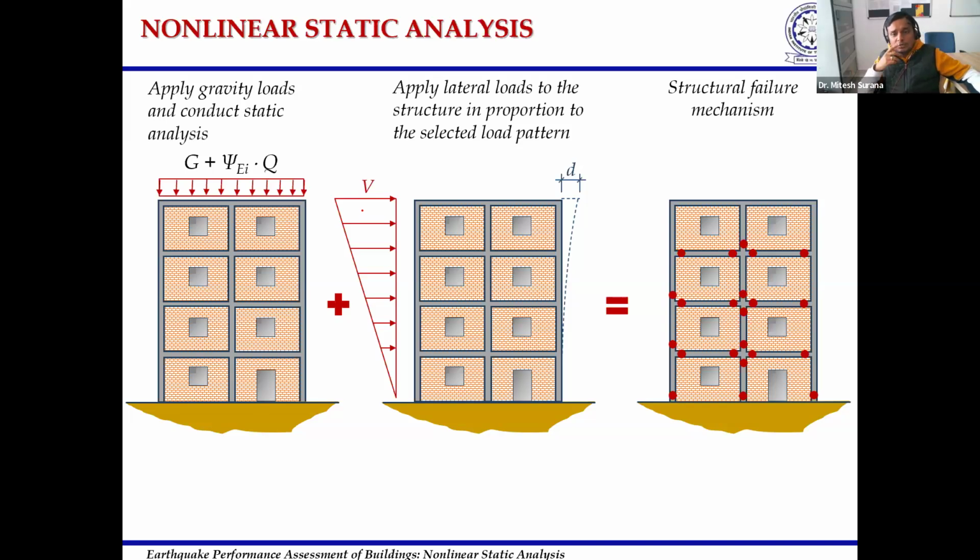So there are certain rules that are established. For example, if the response of the structure is dominated by the fundamental mode of vibration, then loading proportional to the fundamental mode is well enough, because the response is dominated by that mode of vibration. So if you apply the lateral loading pattern in that particular mode only, then your deflections will also closely resemble the actual deflections that are going to occur in the structure.